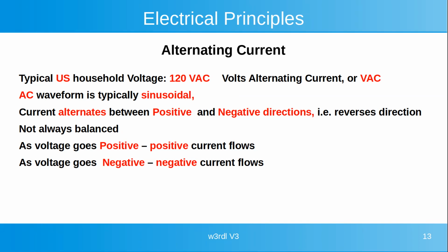So a square wave, for instance, is the sum of all of the odd harmonic sine waves. In other words, say a 1 hertz square wave would be composed of that 1 hertz sine wave, a 3 hertz sine wave, a 5 hertz, a 7, on up to infinity, and actually generate a square waveform instead of a sine waveform.